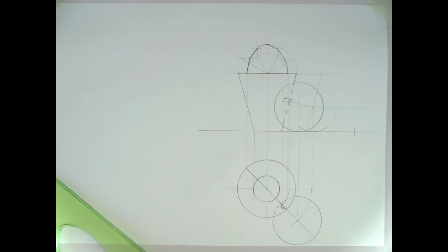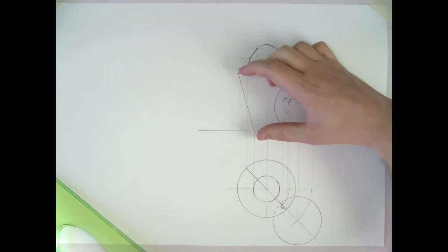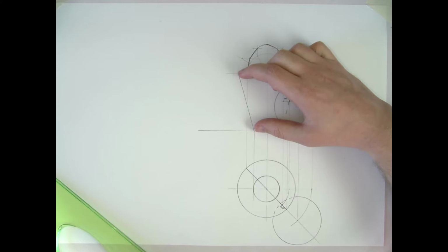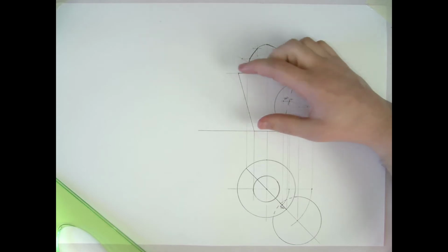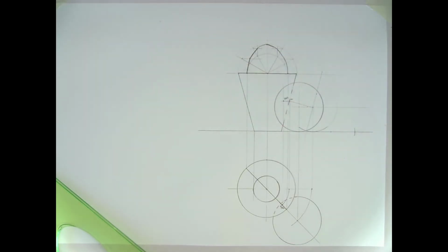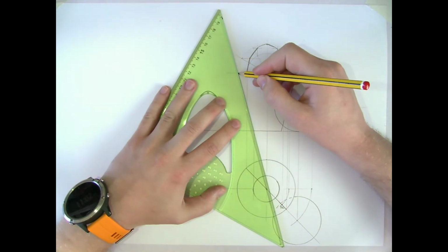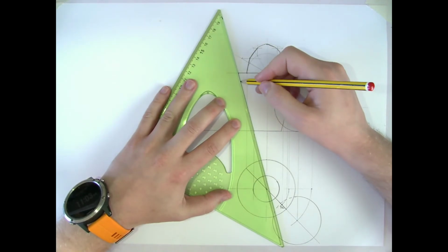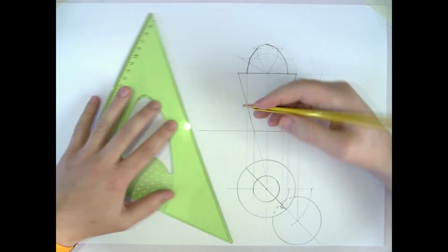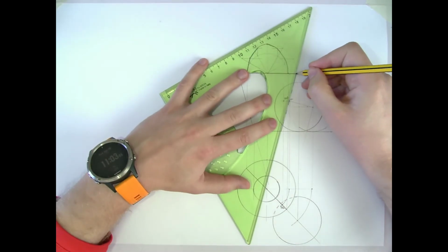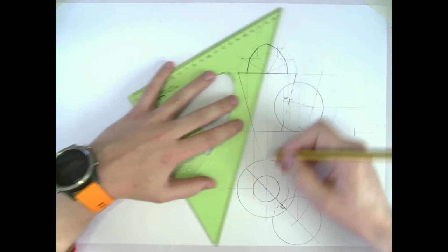So for our conical surface A, we need to find the length of the side of the cone. So what would be the true length of one of the sides? This is a true length of one of the sides, however it's not the full distance that we need. We need to find the apex of the cone, because that's the point for all cones that we would develop around, swing around. So I'm going to extend the side of this cone down, crosses down here somewhere. You could do it from the same side also, they'll meet at the same point on our axis.